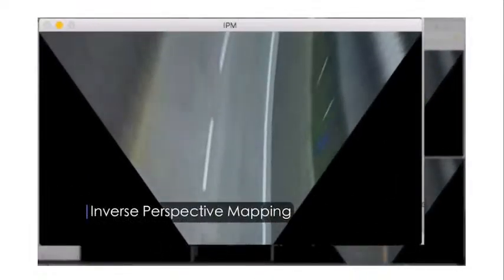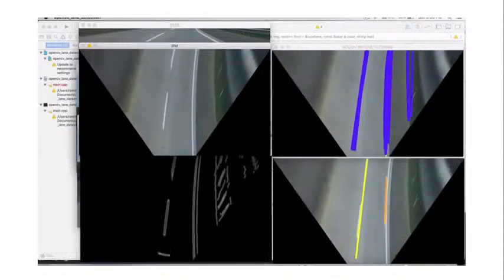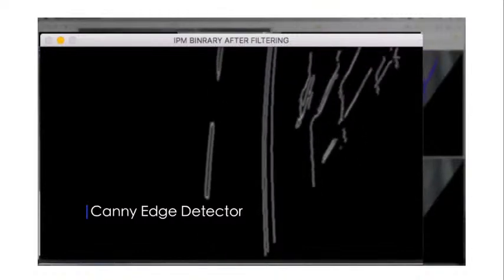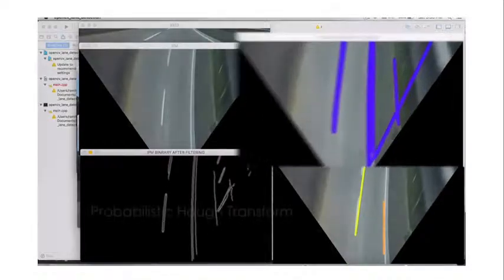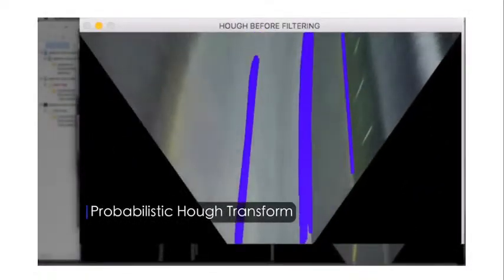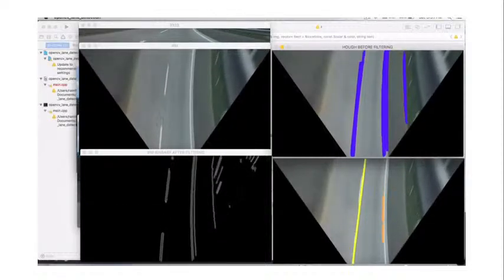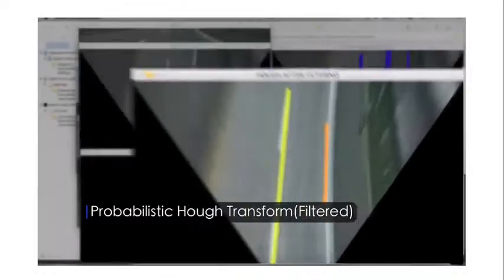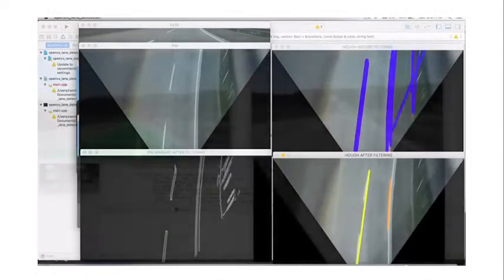For example, take Tesla cars: without a driver the car will drive, right? So here we want to detect that path, we want to detect the lane. For that purpose we are using region of interest, edge detection methods, and the probabilistic Hough transform, which is one of the filter methods, that is also included here, right?